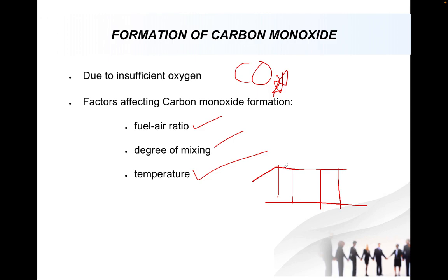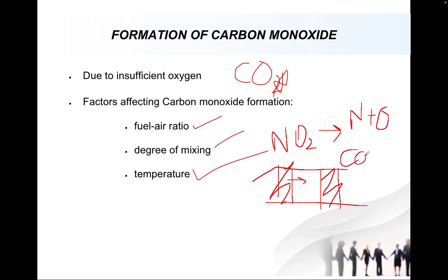In the reduction type of catalytic converter, we reduce the nitrogen oxide. Consider there is NO2, or just NO, it will be split up into nitrogen and oxygen. Coming out from here, it is only nitrogen and oxygen. Now this excess oxygen is combined with the carbon monoxide. So carbon monoxide and one oxygen atom will be added, and it will create CO2. Like that, we can use the catalytic converter to reduce the level of carbon monoxide present in the flue gases.